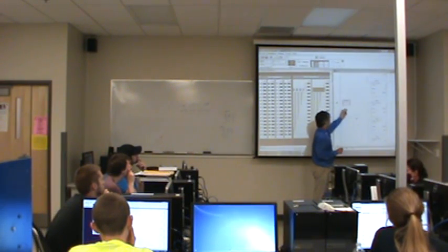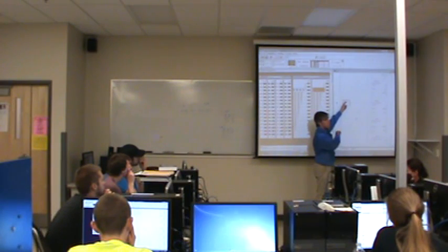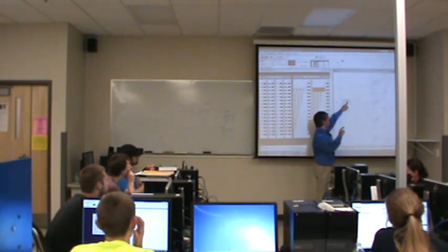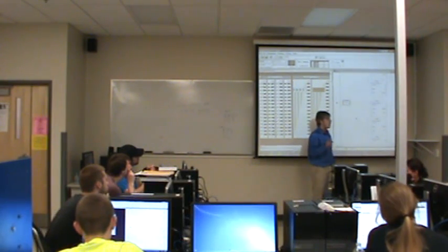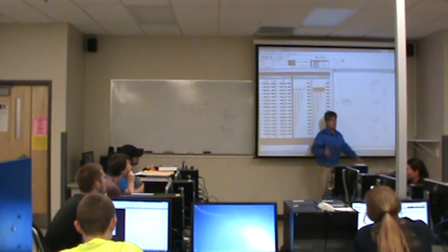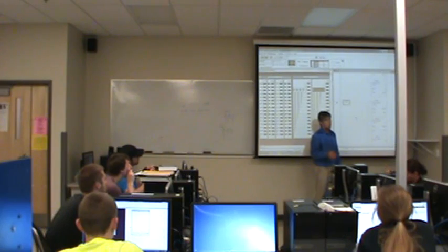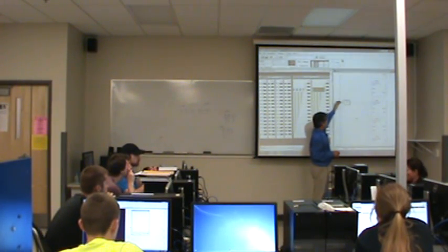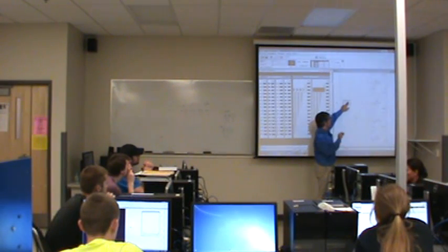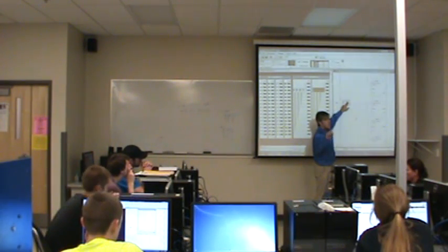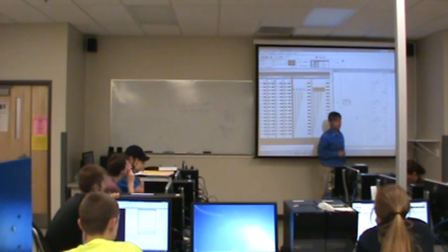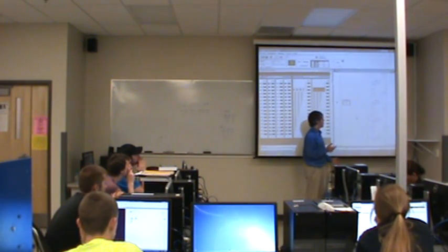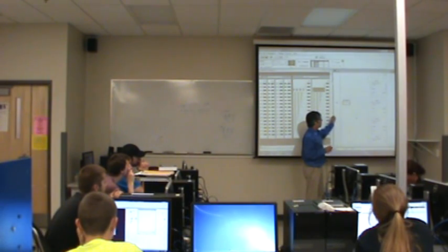So the OSR instruction references a bit in memory. You have to decide what bit you want. What it does is it goes and looks at that bit in memory. If that bit is on, it does not execute this. It just skips it and goes to the next one. It's called a one-shot rising. Basically, if it comes to this address and sees that this bit is not on, it will turn it on and then execute all of this. That way it only happens once. Essentially, you can use it to make something happen once.